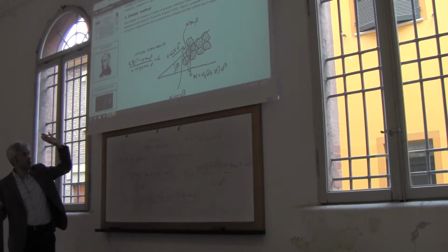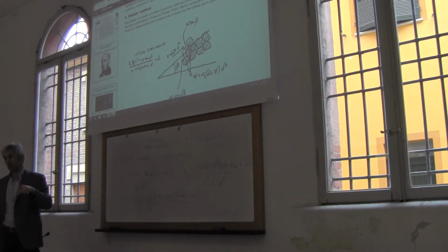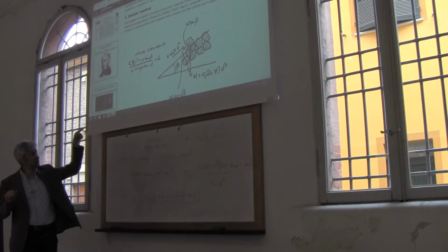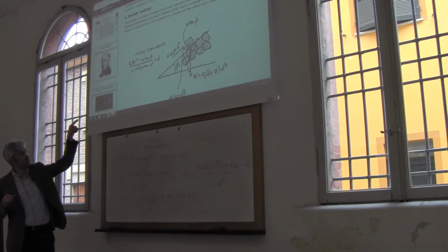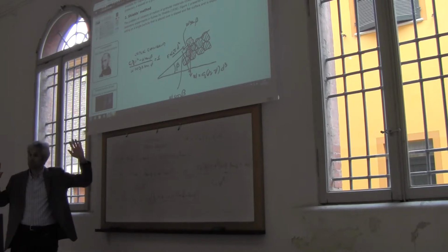The weight of the unit has two components. One is perpendicular to the side, which is stabilizing. The other one is parallel to the side, which is destabilizing. Okay. And then we have another force, which is the hydrodynamic force. We assume it's a stabilizing force, but we also said it can be destabilizing.